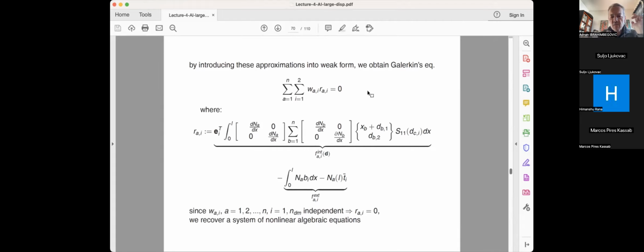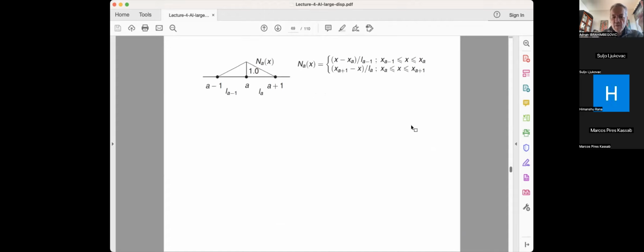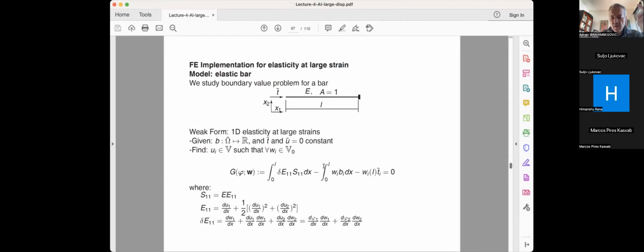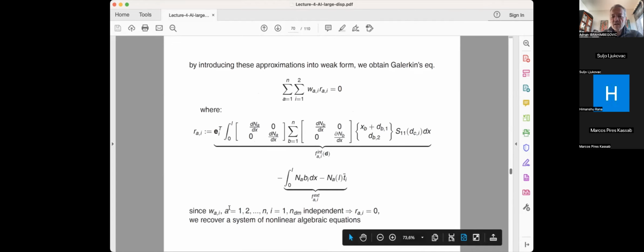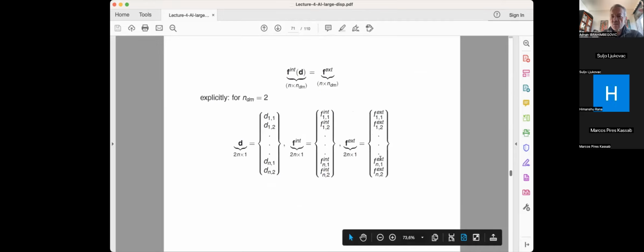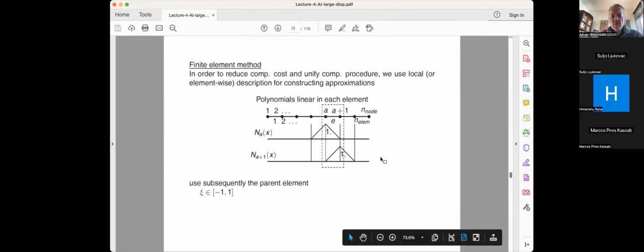So basically this one is already a linear function of displacement. You'll see in a moment, S is a quadratic function of displacement because Green-Lagrange strain is a quadratic function of displacement. Multiplied by Young's modulus, you still have a quadratic function of displacement. So together you have nonlinearity, which is kind of a cubic equation for this type of thing. And this is typical of these.